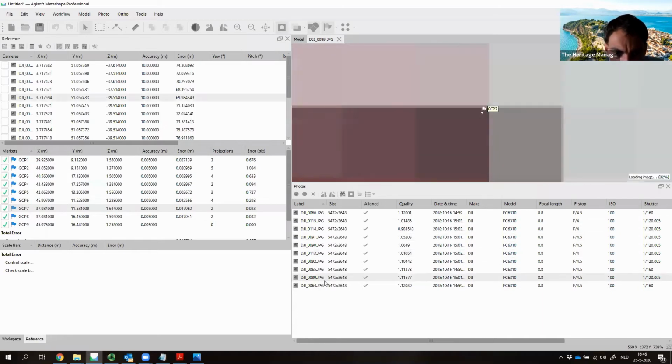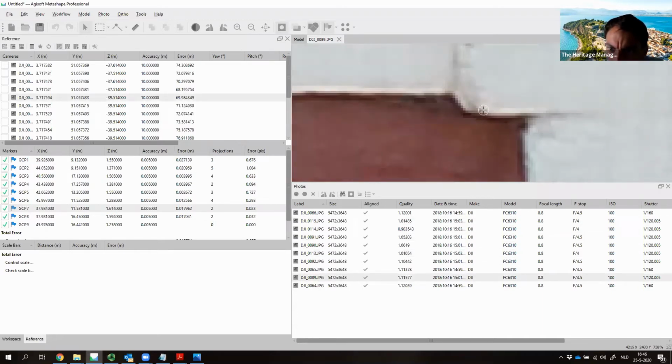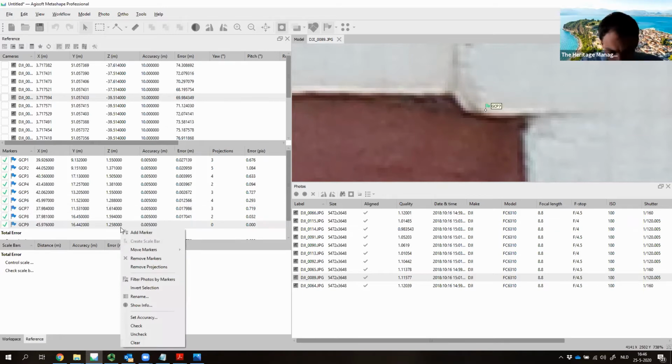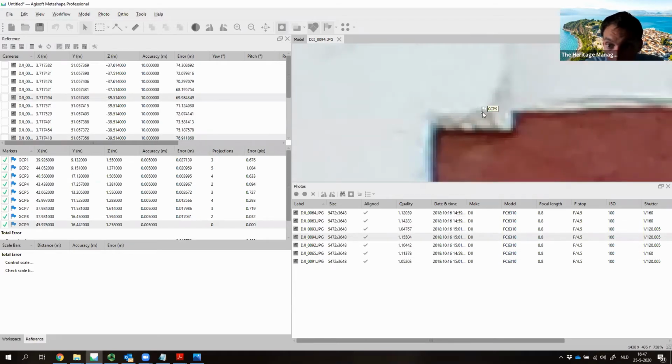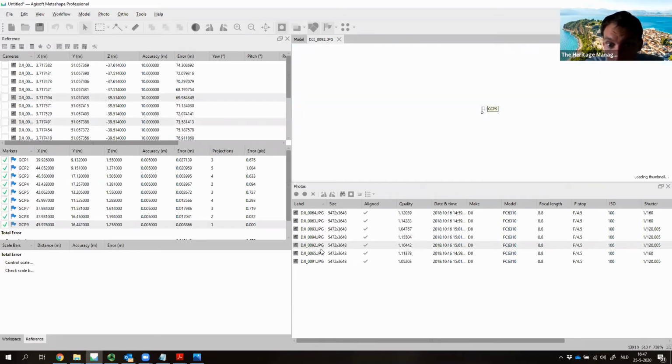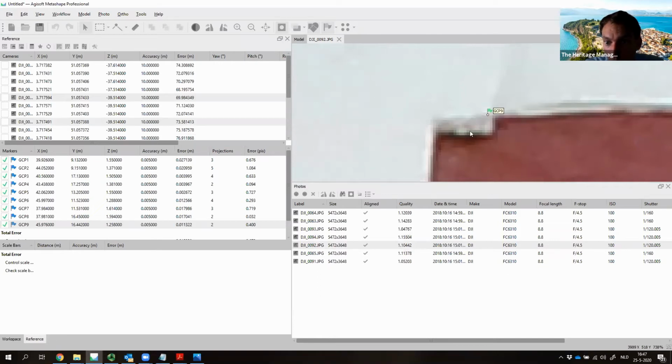Very interesting in this case, especially for the people that are familiar with statistics, mathematics, and maybe even a little bit of land surveying. If you're aware of these techniques, you will know that in order to calculate errors, you need data redundancy. So it means that if you have, for example, 3 points assigned to 2 photos, it actually means that the error that you will see is definitely not meaningful. So you need data redundancy to say something about the quality of your model.